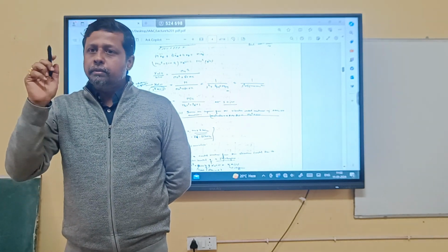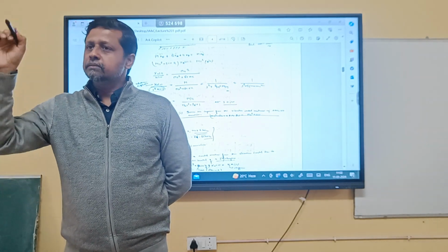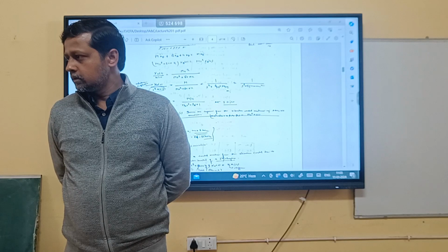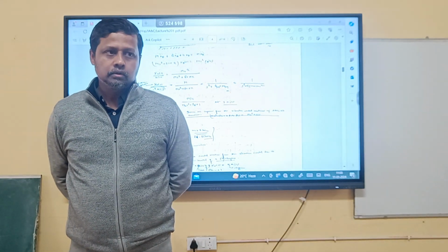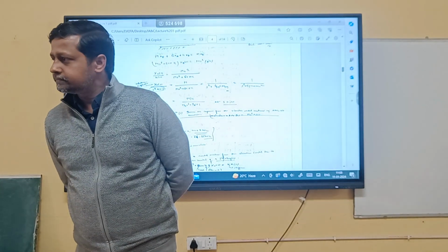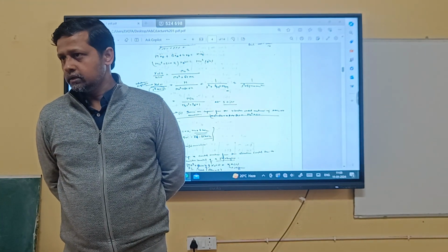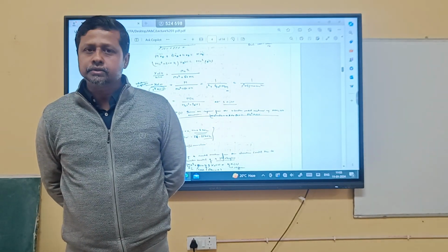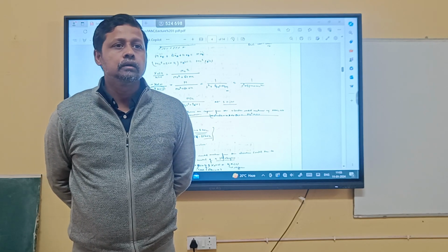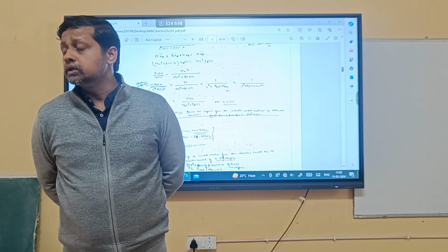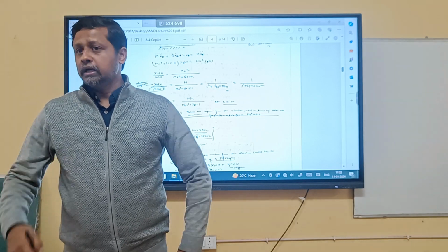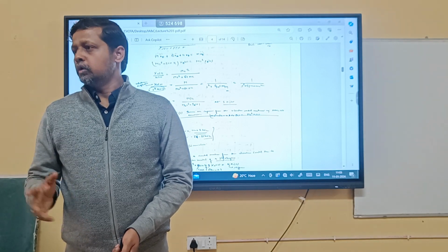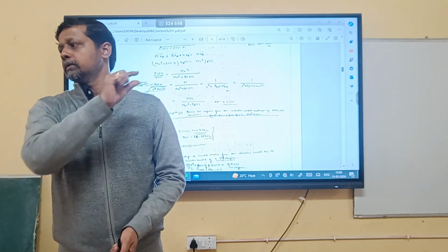So omega n square is equal to k by m. From here I will get my operating frequency. At what frequency can this device operate? Can I get it? Once I get that value, can I get the value of zeta? Can I calculate? Twice zeta omega n is equal to b by m. Omega n is already known. Can I get the value of zeta? What happens from getting zeta? Why do we calculate zeta? Because I need to calculate the damping factor to know whether the system will remain underdamped or not. Because underdamped is the only system which is controllable.